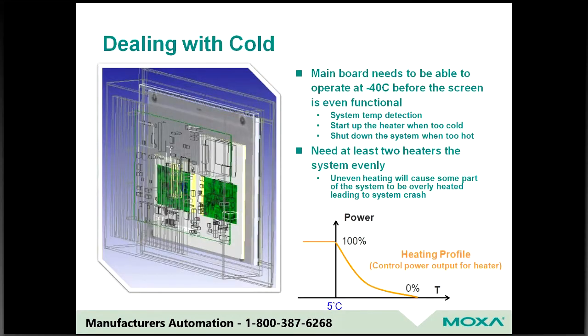Dealing with the cold temperature issue is something that's commonly addressed within heat, which we will also address later, but cold is a separate issue, specifically within industrial HMIs and PCs, simply because heating a unit is much more complicated than cooling a unit, especially for a unit that has a screen, an LCD at that. LCD is liquid crystal display, so that freezes.